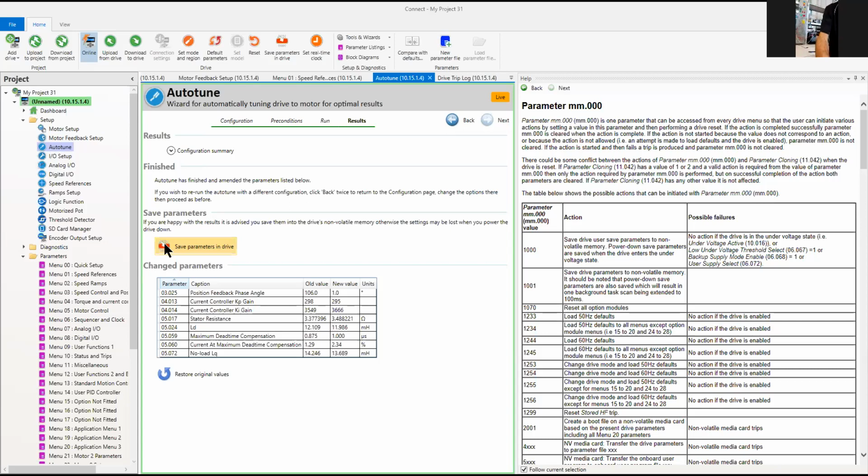So what did we do so far? We changed the motor from induction motor to servo motor, which is a synchronous motor, a synchronous motor with encoder. We applied the parameters for the motor. We pulled up these parameters from the library. We know the information for this encoder.